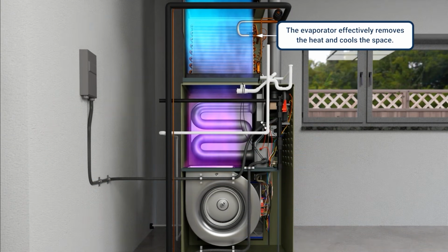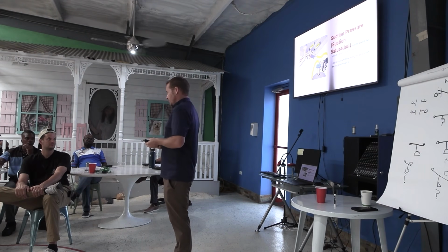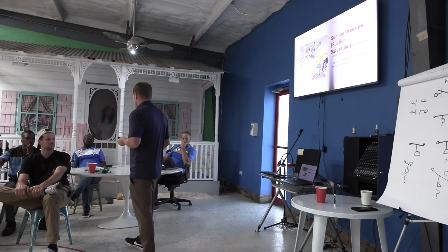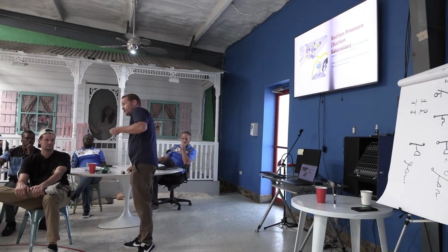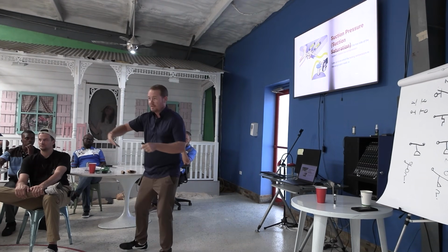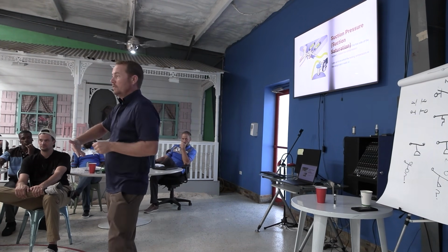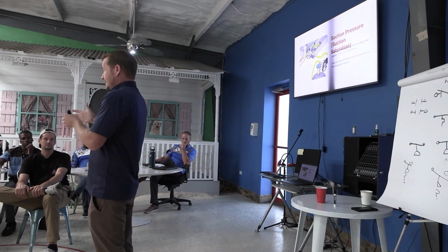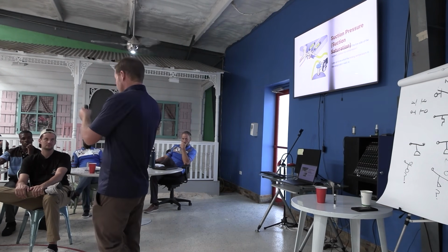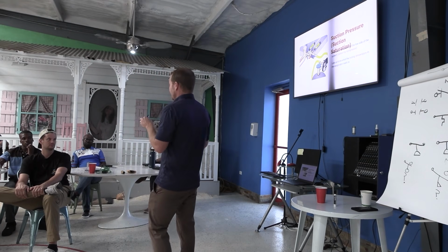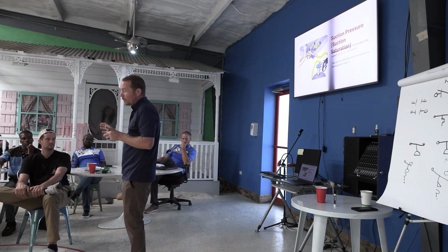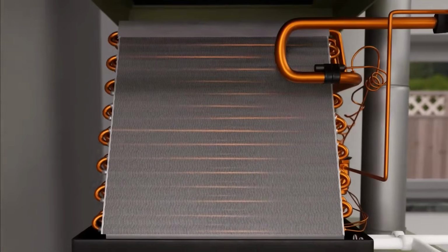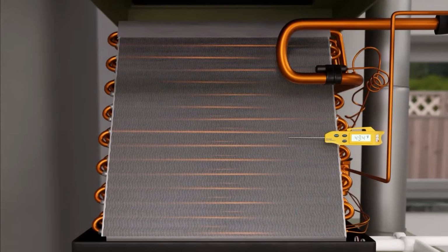Make sense? So what are we measuring when we measure suction pressure? Again, I'm just going to make you say it again: what are we measuring when we're measuring suction pressure? We're measuring evaporator temperature. That's what we're looking at, right? So that tells us our evaporator temperature. Now in this market, my market, why is evaporator temperature really important to us? We know that we don't want to get below a certain number in our evaporator temperature. What is that number?